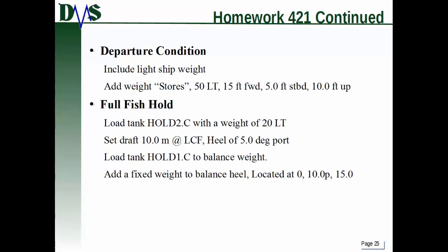Now when you do that, here with the tank load and the fixed weight, you're going to find out that those two are going to start fighting each other. Your trim is not going to balance out, your weight is not going to balance out your trim, and you're going to have to manually issue some solve commands there in the middle as well to solve for draft. So you're probably going to get GHS telling you a few times that it's not happy. And that's something where you're going to have to work it out, and that's intentional, because I want you to work out exactly what sequence of commands you have to use with those keywords.